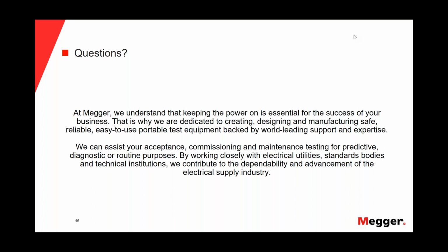As you increase the voltage, you measure the average partial discharge you have in the measurement, and also you measure the maximum partial discharge you get in that specific voltage step. So DP is indeed PD max, the maximum partial discharge in the measurement.